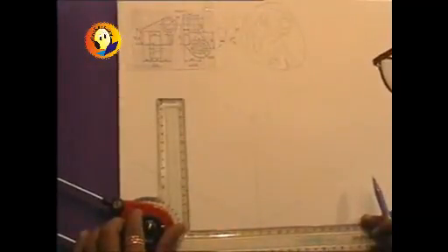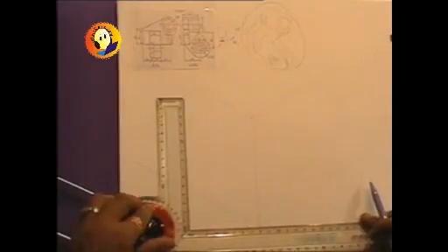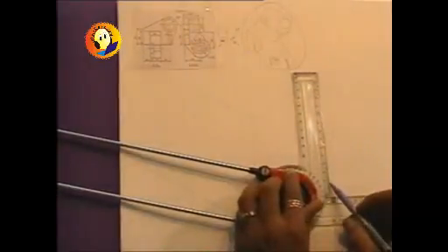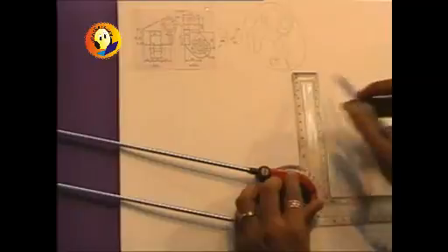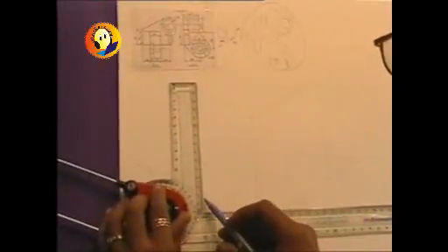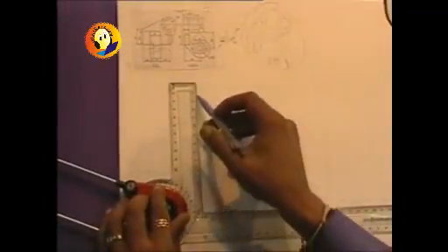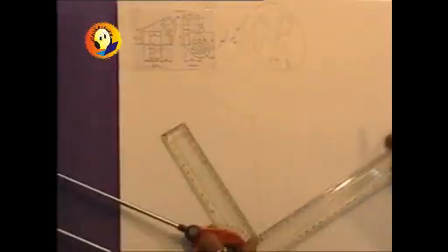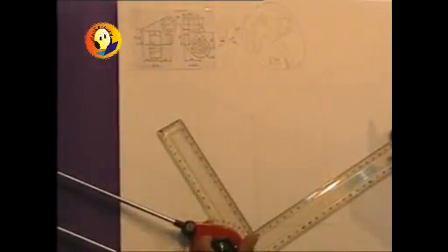That is our very basic principle when we are drawing the isometric. None of the distance which is in the inclined direction, or none of the angle, is to be marked directly. Even the angle should be converted to the distance form only. So I am simply drawing the box, the dimensions which we have already calculated.